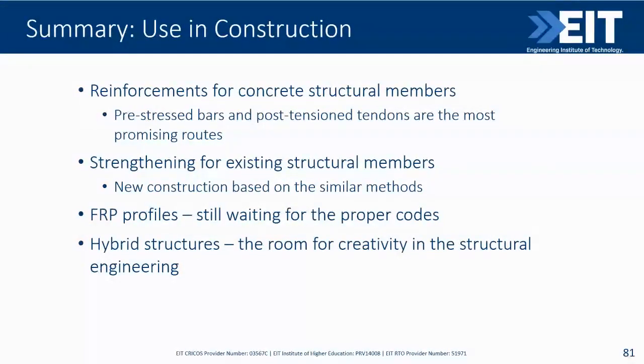They can be used as reinforcement for concrete structural members, and they're already used. But the more potential is in pre-stressed parts and post-tension tendons. The other aspect, which is quite well developed, is the strengthening of existing structural members, and there are some codes for this already. So these methods for strengthening can be extended to the design of new structures.